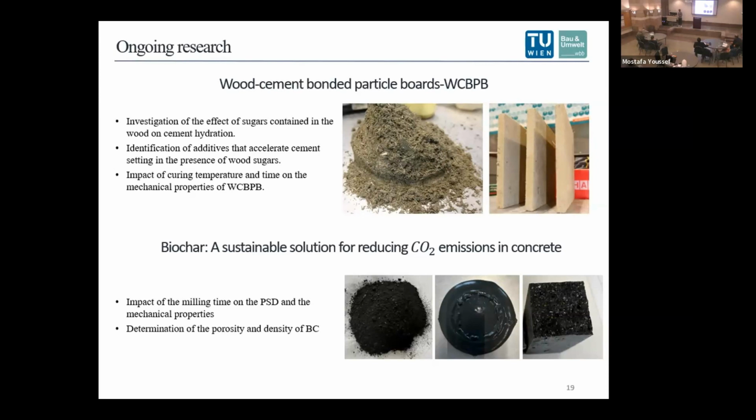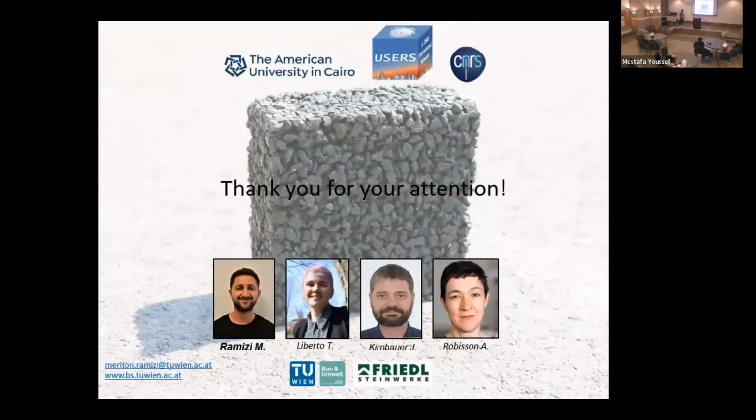The second project is about biochar, and its impact in reducing the CO2 emissions in concrete. Right now, I'm investigating the impact of the milling time on particle size distribution and mechanical properties, and I'm trying to find a way to determine the porosity and density of the biochar fine particles. That was all from my side. Thank you for your attention.